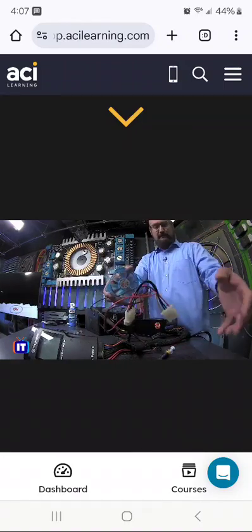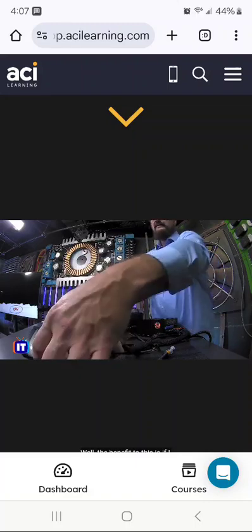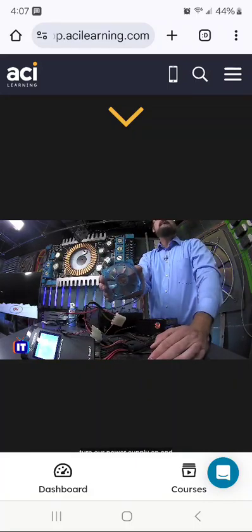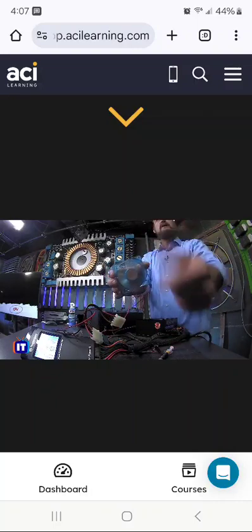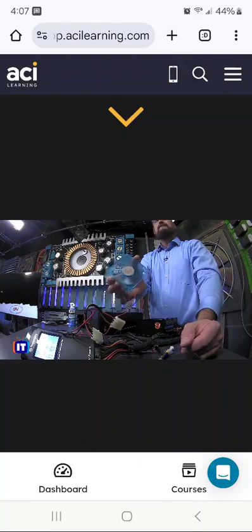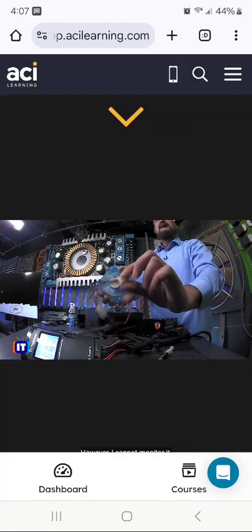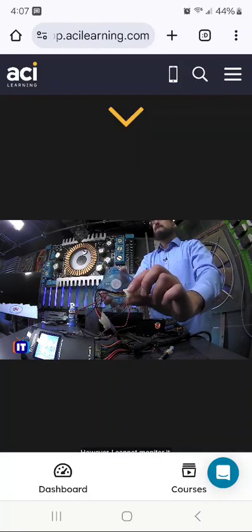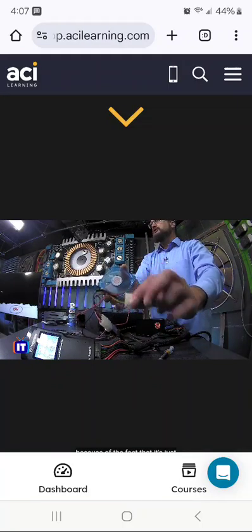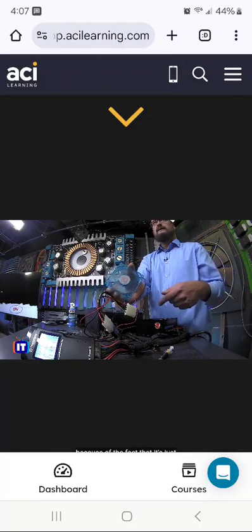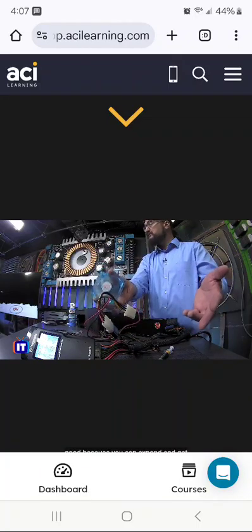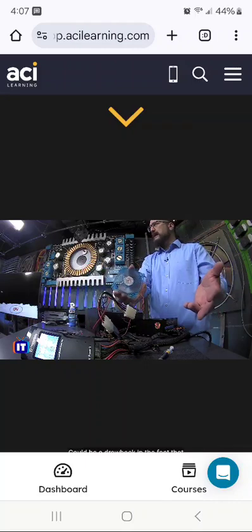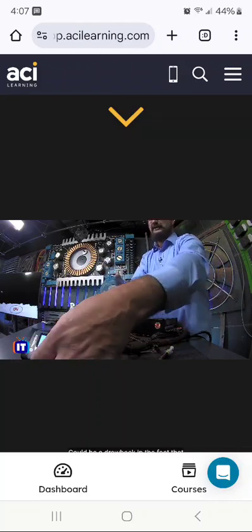Now there's a benefit. What's the benefit? Well, let's go ahead and turn our power supply on, and try that one more time. There we go. You can see the power supply come on. So now our fan's spinning, right? It works just fine. However, I cannot monitor it. We cannot do variable speeds with this because it's just connected to a rail on the power supply. Unfortunately, there's no way to monitor that. Good, because you can expand and get sufficient cooling for your system unit. Could be a drawback in the fact that you can't actually monitor these.